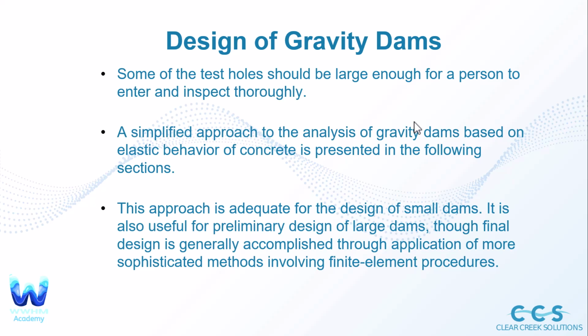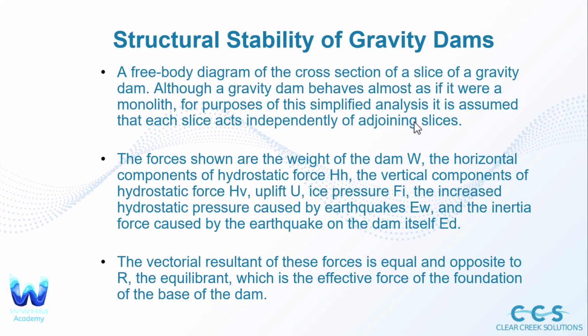A simplified approach to the analysis of gravity dams based on elastic behavior of concrete is presented here in the slides. This approach is adequate for the design of small dams. It is also useful for preliminary design of large dams, though final design is generally accomplished through application of more sophisticated methods involving finite element procedures.